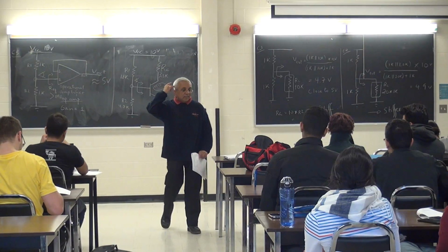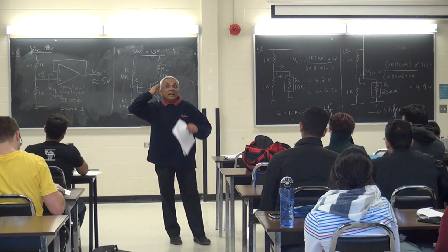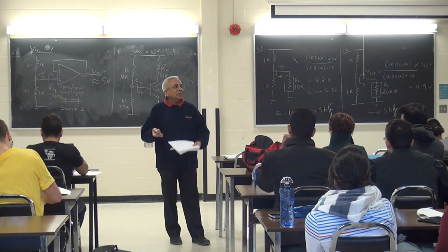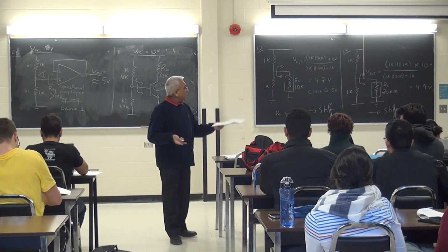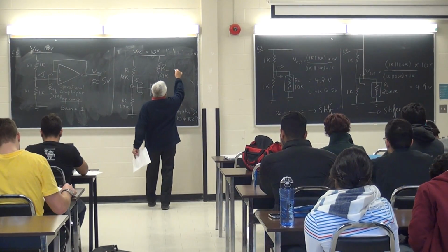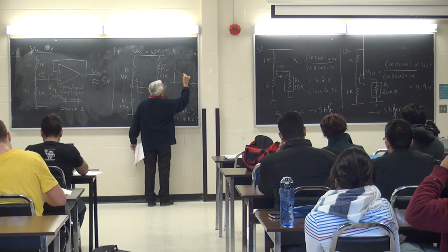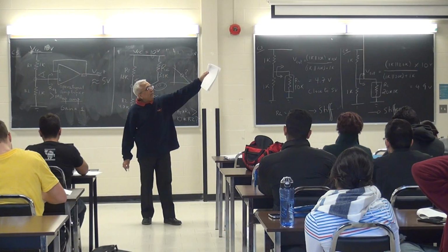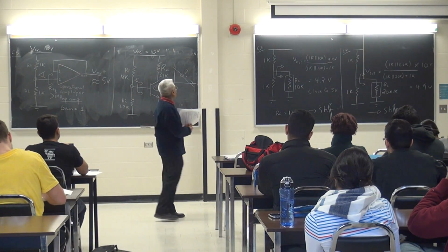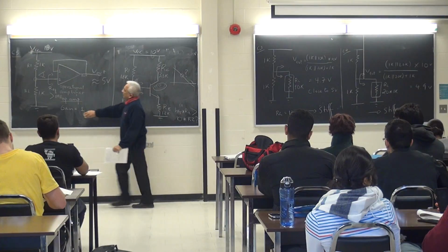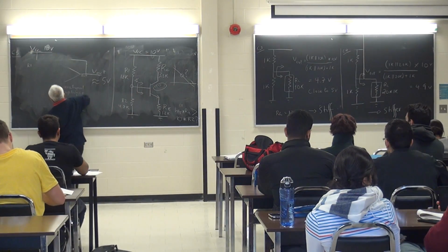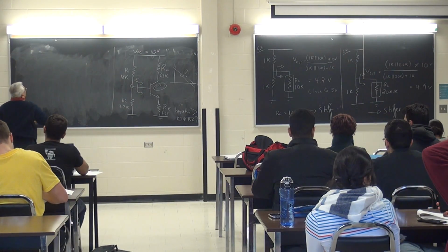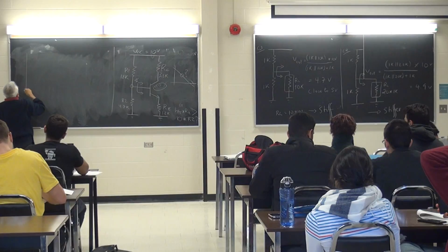Those are the values. I'm going to analyze this circuit, and the whole aim is to find the Q point. That's what I'm going to try to calculate: draw my load line and find out where the Q point is. So first thing is to draw the line.